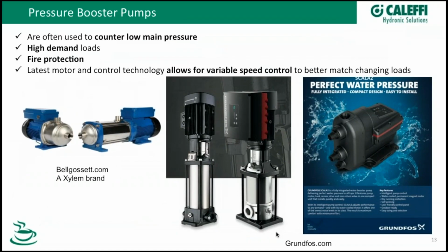And I thought these are pretty good examples of typical pumps that you see out there. This almost looks like a small shallow well pump. Basically, that's what it is, but it could be used as a booster pump. And so when they build these, they can change the number of stages that they put in here to change the capacity of that pump, change the motor, change the size of the connection. So when you get into these larger sizes, these really are custom built to the application.